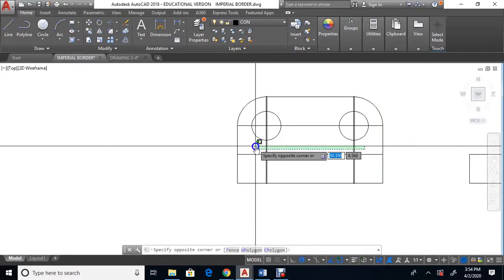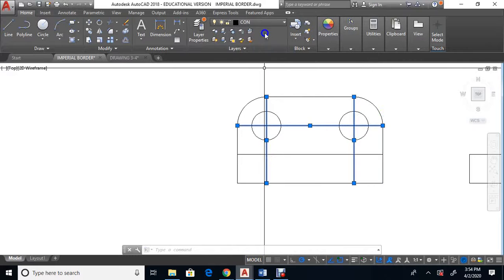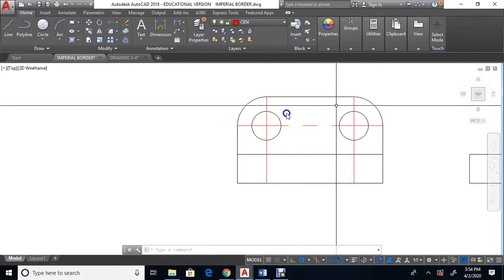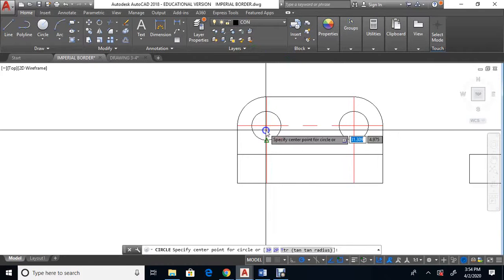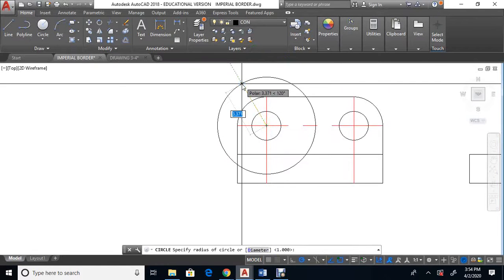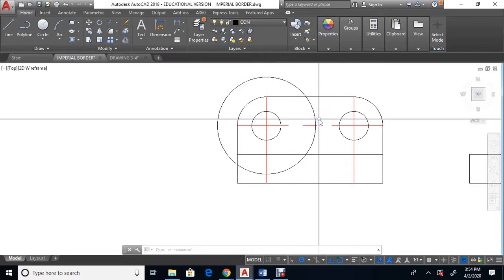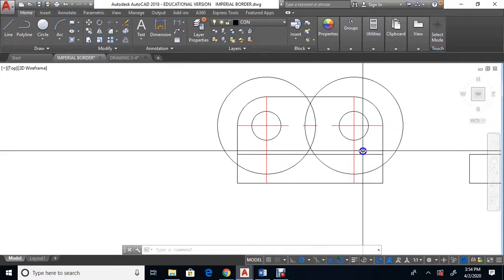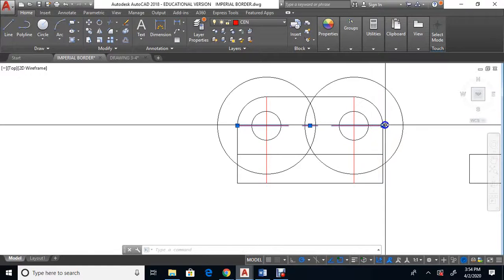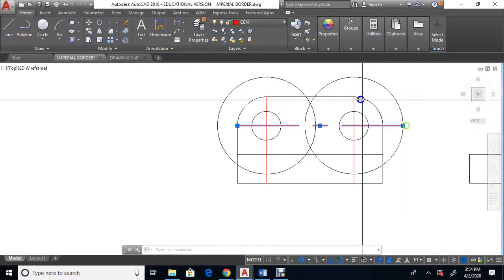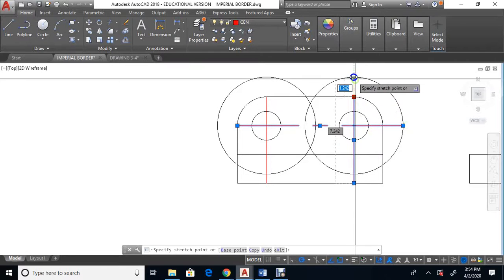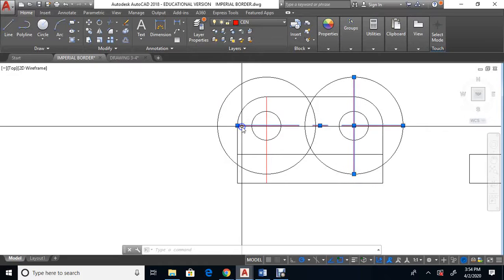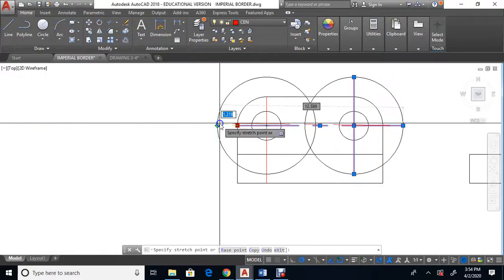Okay, these lines are going to turn into center lines. And center lines should not touch the edges. So I'm going to make a circle, and I'm going to extend those lines further, and I'm going to make another circle and trim it at the bottom. I'll make another circle here. Okay, and I'll just grab these pick points here. I'll bring one there. I'll bring that one up here. I'll bring this here so it doesn't touch. Okay, we'll bring that pick point over to that quadrant.